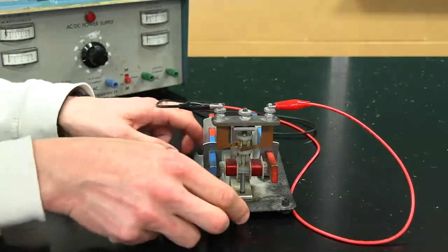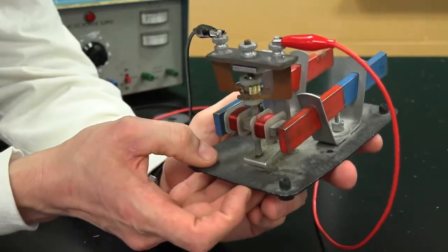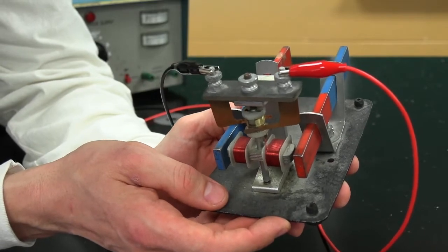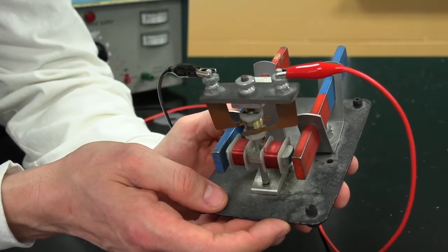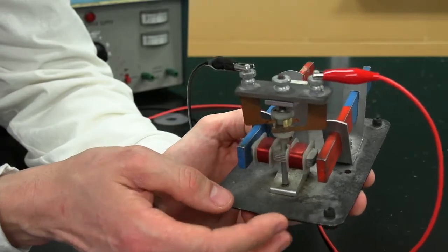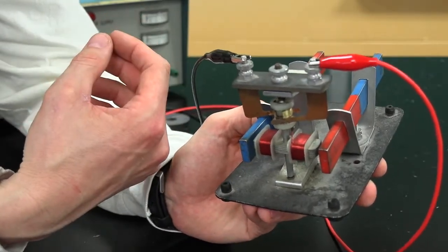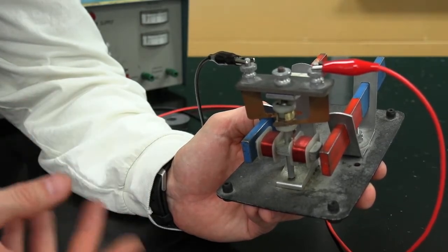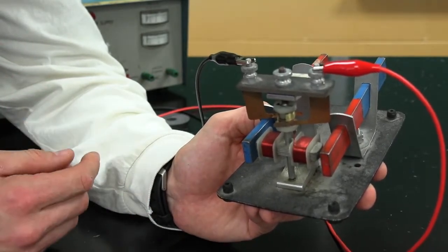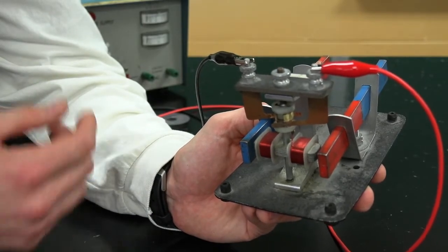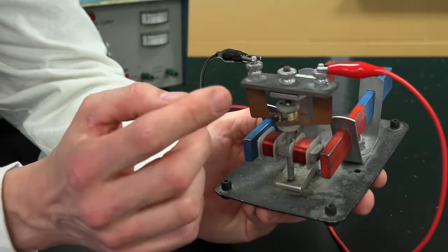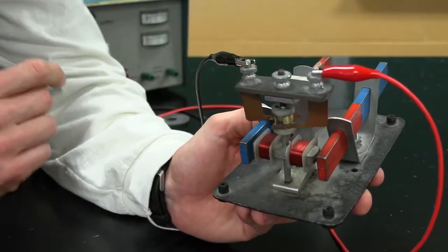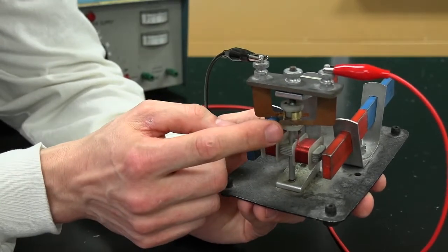What I have here is a device that's essentially a very crude electric motor. It's not designed to do any useful work other than to spin and show you the principles that work in an electric motor. Now, as we saw in the previous demonstration, if I keep switching the direction of the electricity in coils, I get the coil to flip in the horseshoe magnet 180 degrees over and over again. So this doesn't cause the flipping by switching these wires manually up here. It utilizes what are called brushes.